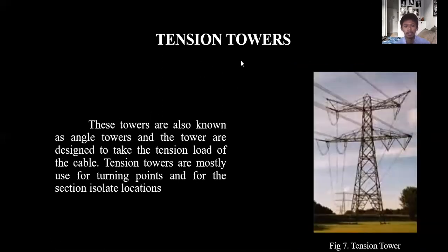Number two is tension towers. These towers are also known as angle towers, and the towers are designed to take the tension load of the cable. Tension towers are mostly used for turning points and for the section isolate location.